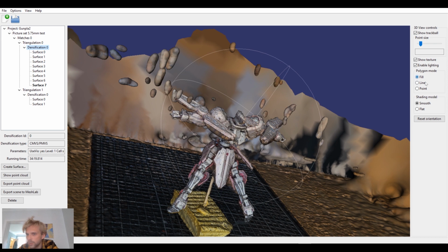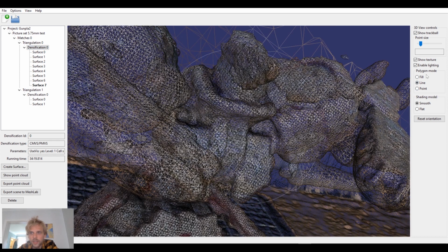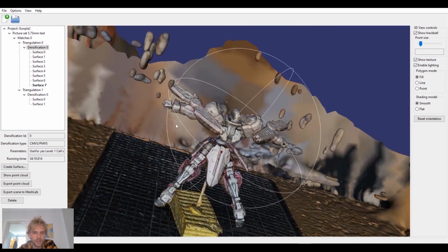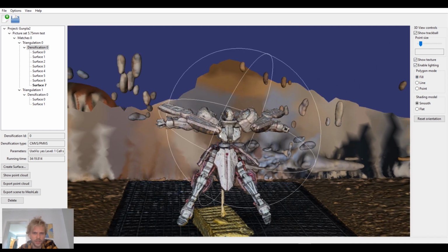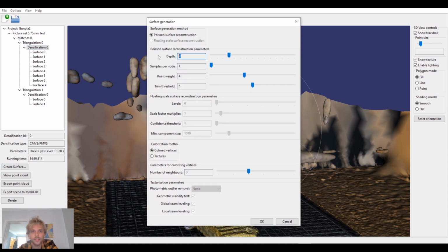And it's quite dense. If I zoom in, you can see all of these polygons here. So I wouldn't suggest going beyond it, right? Especially for something small like this. Okay, so we have that going on. Now, this one was 12, right? Why can't I write it? 12, hello? I can only increase it like that. And it's also an exponential growth in the amount of polygons. So if you increase the slider even more, it's going to crash your computer.